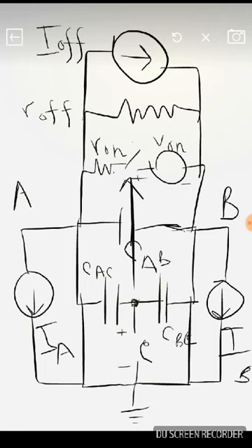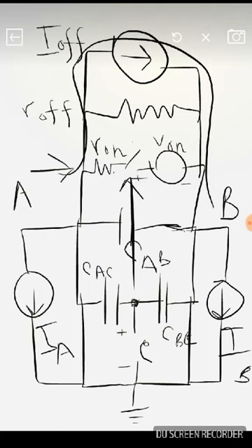Suppose we have given a data at A and we want to have the data at B, and the switch is off. So this circuit is not transferring any data, or the circuit is open-circuited. So where does the current go? Actually, if it is an ideal switch, then there should not be any leakage current. But there is nothing called an ideal switch. So in a real MOS switch, there is a leakage current, this I off, which goes through this path. This is the I off path.